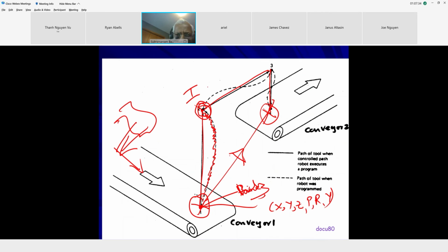So I moved along this dotted line, wavy or whatever, capturing every little blemish in the path that I generated, but I did not record any of these. Once I reach this, I tell the controller, hey, capture, let's say this is X1, Y1, Z1, P1, R1, roll 1. Now capture X2, Y2, and so on. Store it in the memory. Same way do this, X3 and X4. So I only capture 4 positions.